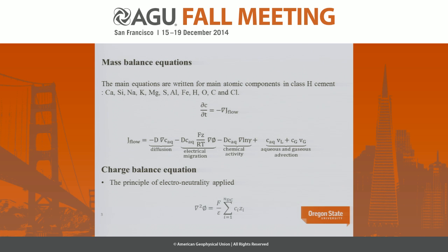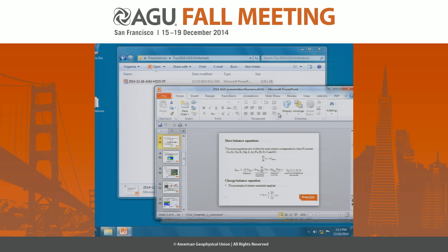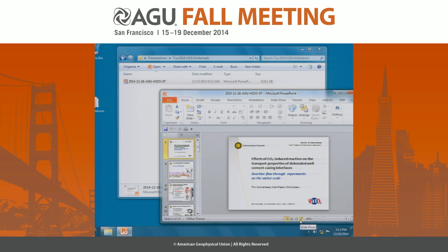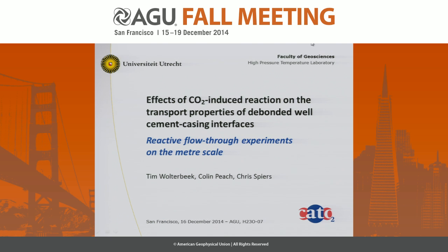But what about change in porosity? We have a reaction part. At one step of the analysis, we find the result of, for example, hydration or carbonation, and the solid phases have different volumes. So the porosity is changing based on the precipitation and dissolution of different solid phases. It means that porosity is time dependent and space dependent. After that, the tortuosity is changing, the saturation degree can change, and all of the other related parameters can change.